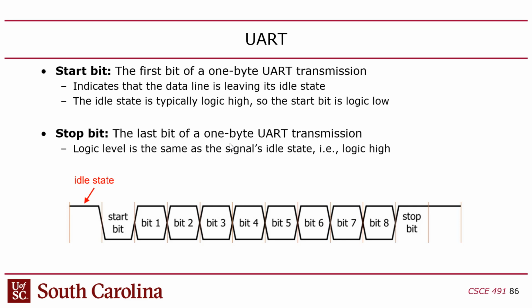The way a transmission is indicated is through a start bit, which is logic 0 for 1 bit time, right? The problem is, what's a bit time? Because there's no clock, how do you know what the bit time is? Well, it uses a kind of insane approach where you just have the two sides of the channel agree ahead of time what the speed of the channel is, and that's called the baud rate.